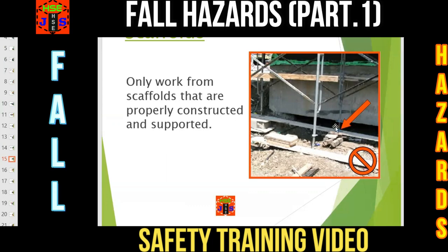Do you think this is a properly constructed and supported scaffold? Absolutely not. This is unsafe. There is no mud sill, there is no base plate. There are a few wooden pieces, maybe scrap, and the scaffolding structure is footed on an unstable surface. So this kind of work practice, this kind of scaffolding erection, is totally unsafe, and no one should access